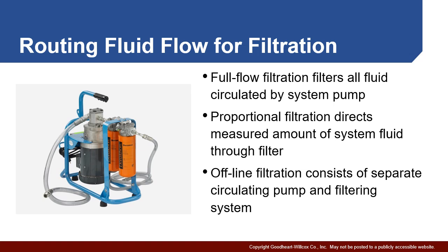Another option, particularly if you have a large amount of contaminants, is to use an offline filtration system like the one shown here on the left. This would be something you'd connect up to your system, may run, say, at night or on a regular schedule, and it has large filters on it, its own separate pump and motor, and essentially it has a much larger contaminant holding capacity. Some of you may have experienced this if you ever worked in the fast food industry. They use a similar system to actually filter the hot oil in a fryolator to eventually clean out all the contaminants. So it's not just necessarily something from the hydraulics industry.